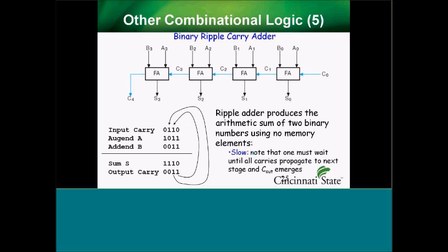Now, if I want to actually make a ripple adder, which just goes bit by bit, carrying up, which is more or less how you add when you put it on paper, you have a carry in to one stage. You add A0 and B0, that gives you the sum. It kicks out a carry to the next one, A1, B1.